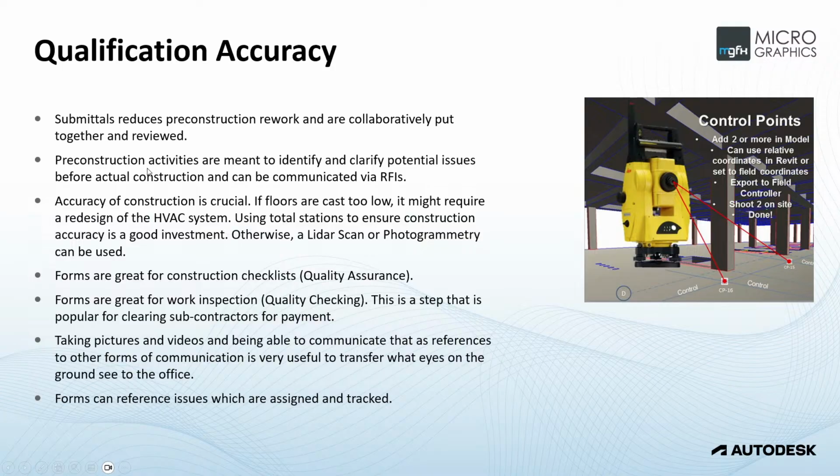Then pre-construction after that. It's meant to identify and clarify potential issues before actual construction, and can be communicated via requests for information. Now, if you had done your design work and your submittals correctly, then there would not be pre-construction issues that appear, and the guys in the industry hate pre-construction work because it really comes out of their bottom line, which means that it's not something that's actually paid for. It just subtracts from the profits during the project.